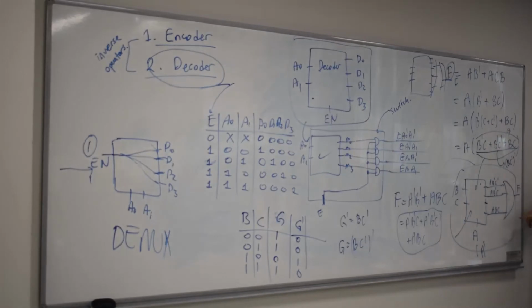Okay? So, of course it would not work here. Why? Because we didn't have A. Forget about A. So the function would change, of course. I'm thinking about only G, right? Then instead of ORing these 3 inputs, I'm going to just put a NOT gate here and then push it out, because that's exactly identical to these 3 min terms. It will not work here. Why? Because A also comes in with that input. If you negate or invert that, A will also be inverted, but A is not part of your function. That's why it's not going to work here. But if we had